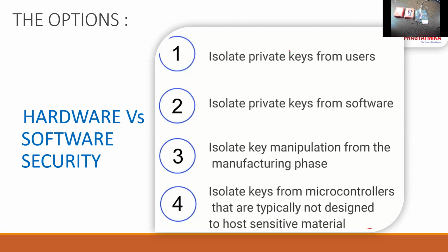They remain connected through the SPI interface. That memory is extra, outside of your core, because ARM is only the core, and thereafter we have the housing for the complete microcontroller. Those memories could be easily compromised, and that's why microcontrollers are not designed for hosting such data.